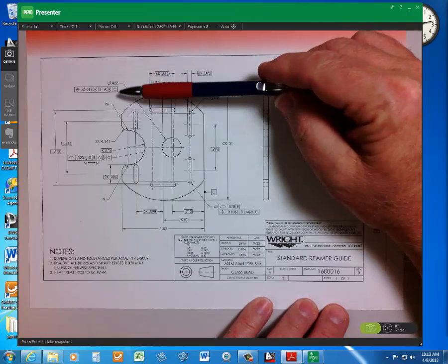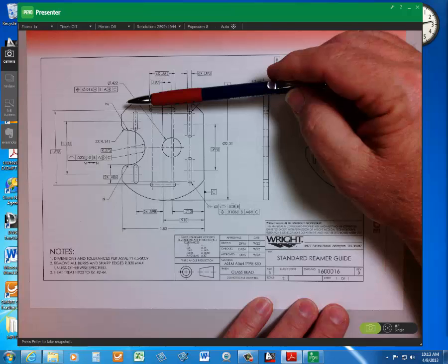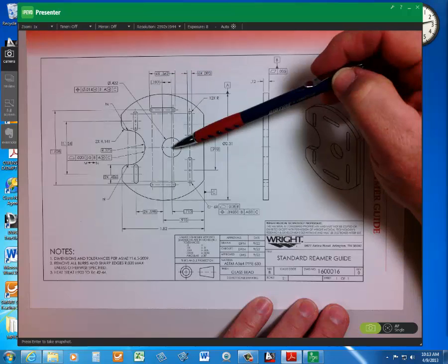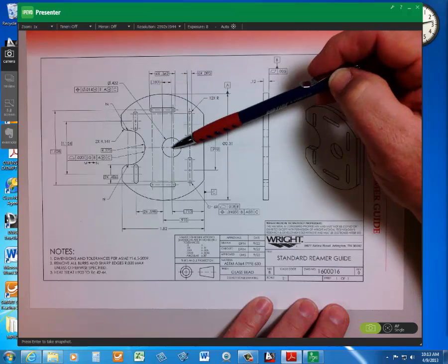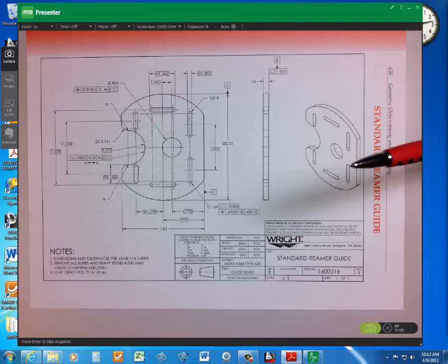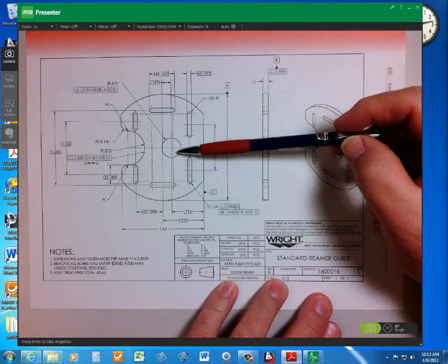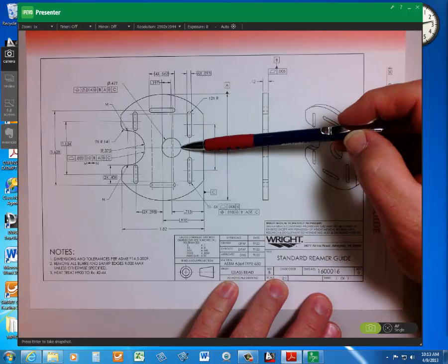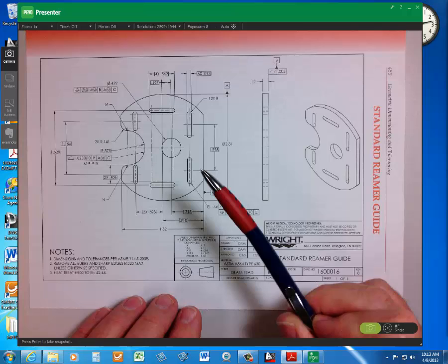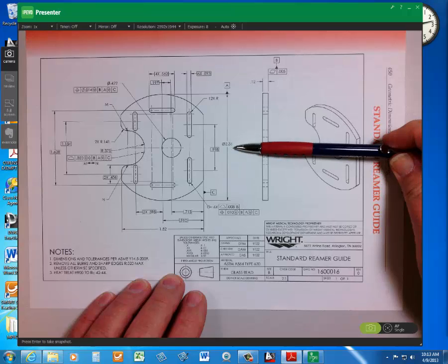Then we move up 5 thousandths. Position tolerance changes to 0.019. Virtual condition is still 0.403. Virtual condition, remember, is the combination effect of the tolerance of the position and the size of the part. By using virtual condition gauging, we can check for location and size of the part, mainly for location, by using a pin located on center 0.713 and this at max material condition.